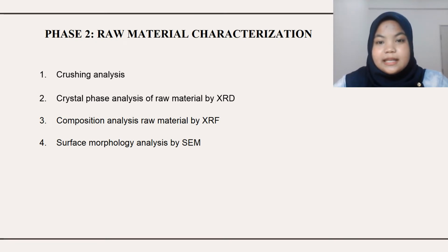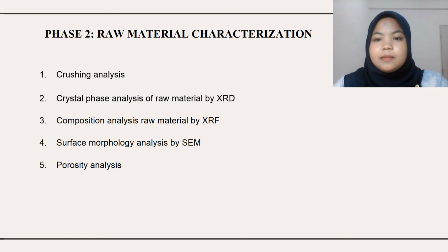Lastly is porosity analysis. It is done by measuring the volume of gas that physically bonds to the solid surface at various pressures. The suitable gas in this analysis is nitrogen gas. This technique characterizes pore size distribution independent of external area due to the particle size of the sample.